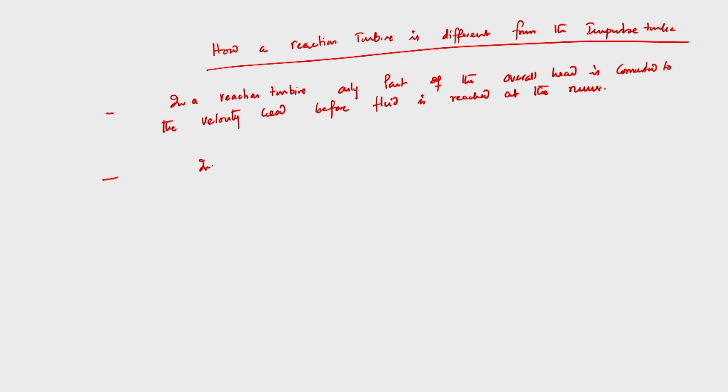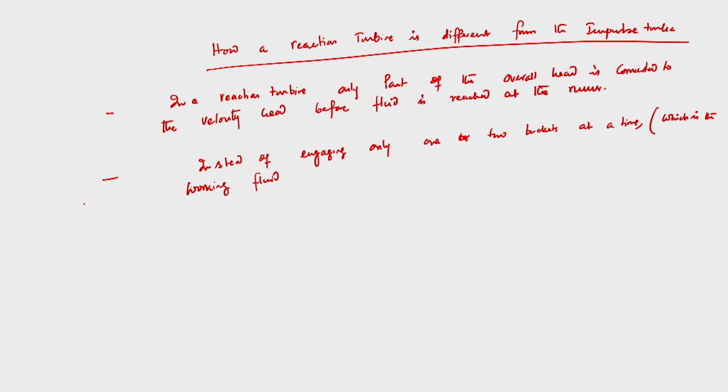So instead of engaging only 1 or 2 buckets at a time, which is the case of an impulse turbine, in a reaction turbine the working fluid completely fills the runner, completely fills the entire runner passage.